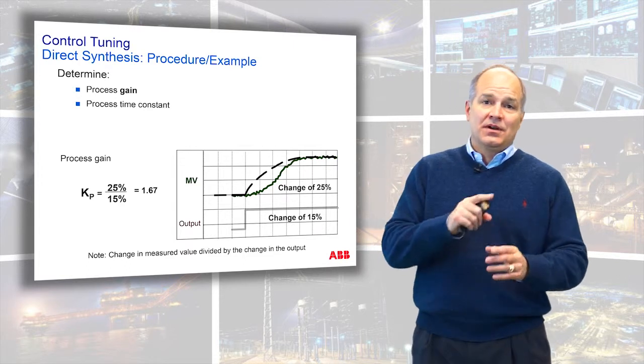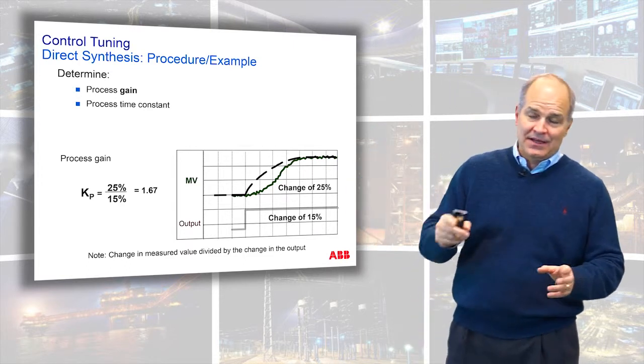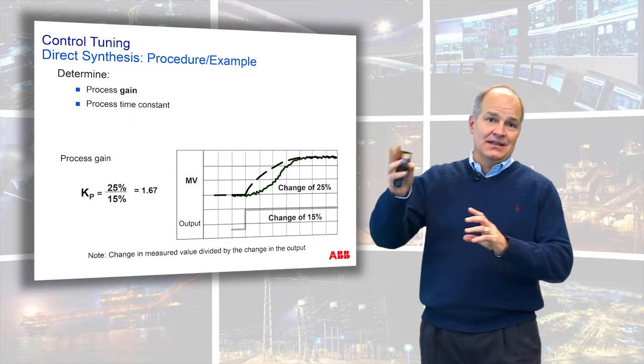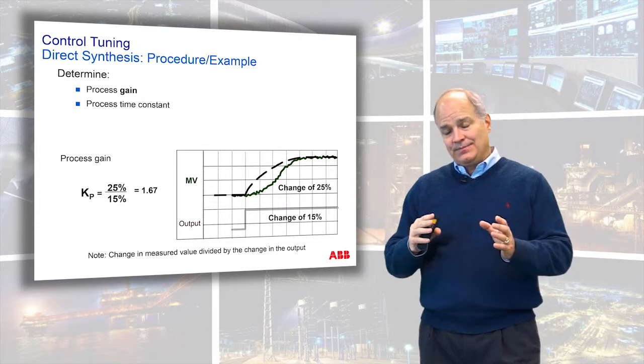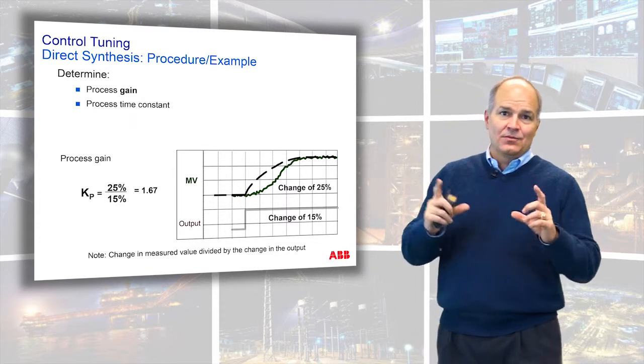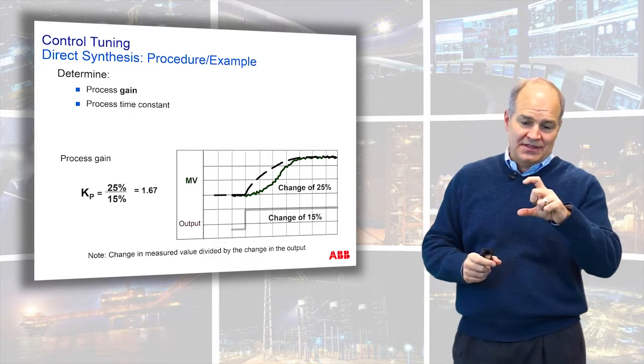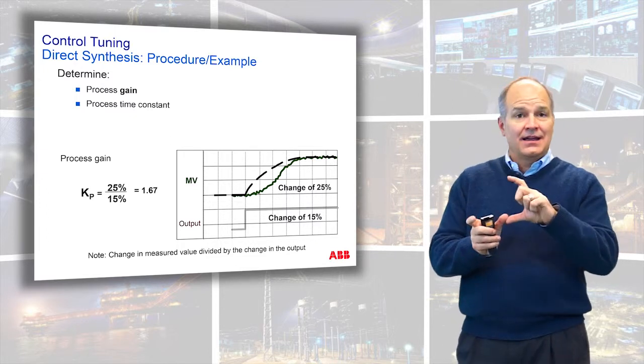It correlates well to valve position. I've been in other places where, with your valve, that 30-60-90-10 rule is that between 30 and 60% of your valve, you get 10 to 90% of your range.